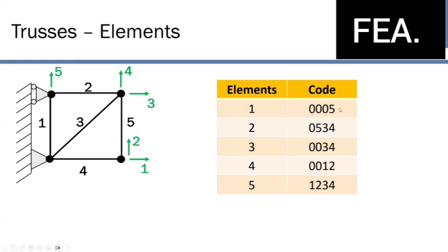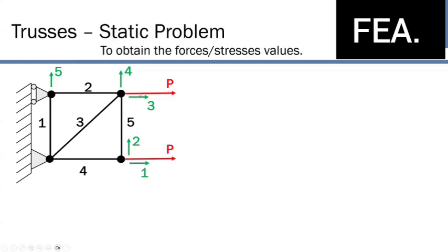So now we're going to apply external loading to our problem. This system is now going to have 2 point loads here, 2 P's, one at this joint and one at this joint, just external loads out to the right, right? So now we're going to pull out statics. We're going to go back to equations of motion, trying to solve for our unknowns. Our ultimate objective with this is to identify our unknowns. So in this problem, how many unknowns are we going to have, or at least reaction forces? Anybody? 3, right? So we're going to have R1, we're going to have R2, and then as you guys remember, the pin is the one with 2 reaction forces, right? So I'll just call this R3, right?